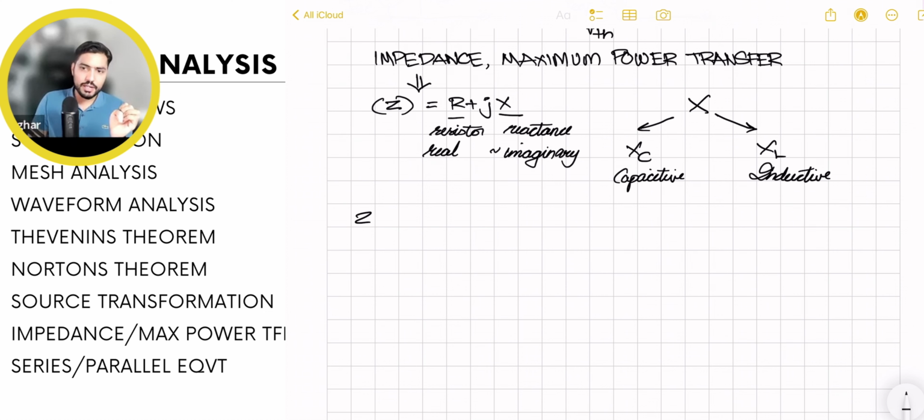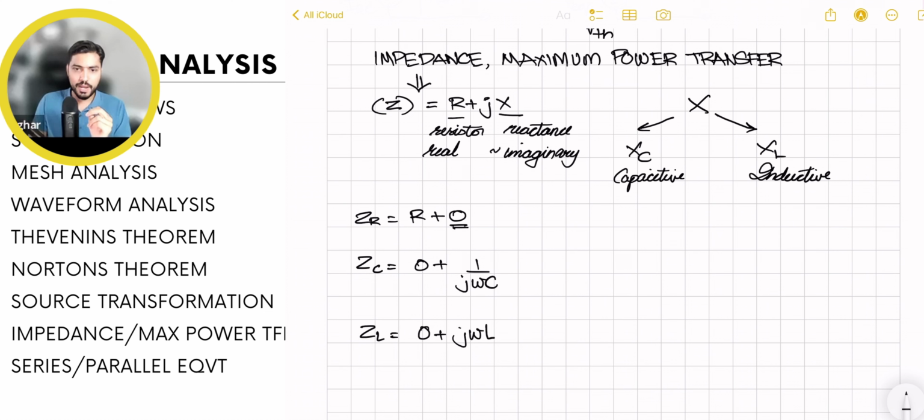So for the inductor, the inductive reactance is equal to omega L. The reactance for a capacitor is sometimes a little bit tricky for students to understand because it does a little bit of gymnastics with j. I've explained that in the course, but it is -1 divided by omega C. And for our resistor, we don't have any imaginary component, right? And then the reciprocals, susceptance, conductance and admittance, all of that is also defined.